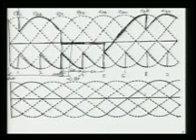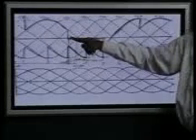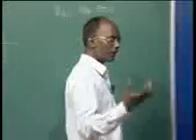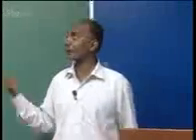So it is a complete cycle. The valve voltage you can see here, it was coming here, EBC here, and again the cycle is completed. So EBC, and suddenly EBA is following. Once 3 is getting a pulse, suddenly it is 0 and then it continues, and this is your voltage. So this is valve 1 voltage. Similarly you can draw valve 3 voltage, and similarly the voltages of any of the valves.